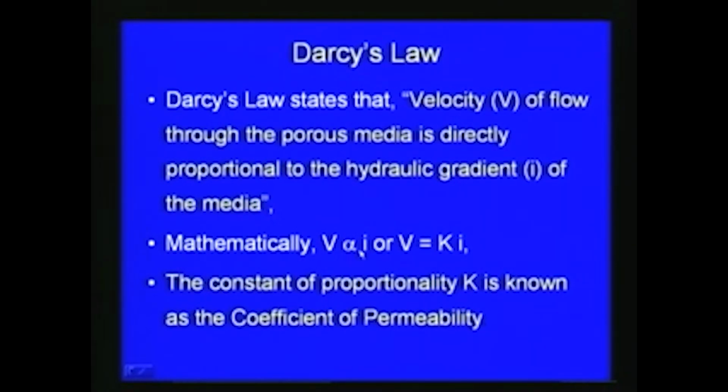Mathematically we can write V is proportional to I, where I is the hydraulic gradient, or we can write V is equal to K into I, where K is known as the coefficient of permeability. K is called the coefficient of permeability.